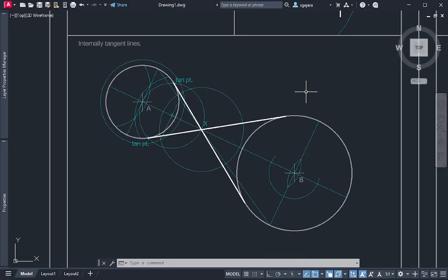Okay? So which do you prefer, the long method or just the tangent point? But you have no choice, for a shortcut, it would be finding the point X. You really have to do that. You need to find point X because we need it to establish where we will consider it as if it were a point. If you find point X, then you can use the automatic OSNAP, which is tangent point.